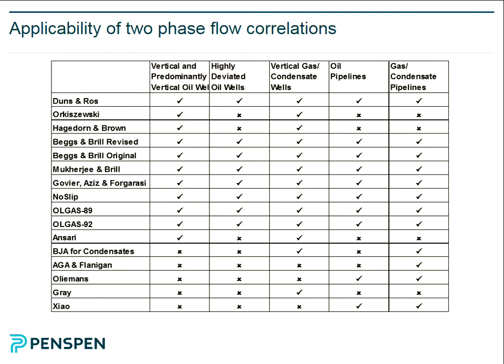And for a multi-phase flow system, as the flow rate increases, you'll find the hold up will go down, and the more efficient flow regimes will be promoted, like mist type flows, slug type flows. So in multi-phase flow, the higher the flow rate, the more efficient it is, and the more it relates to single phase flow. They get closer together as the flow rate gets higher. So that's an important comparison.